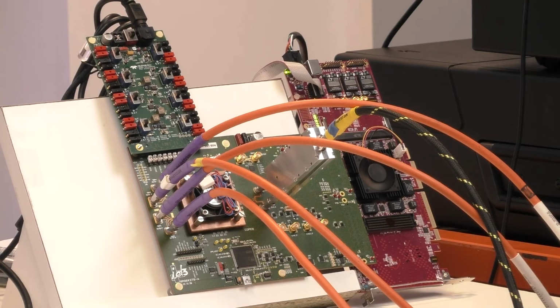Here, in our case, we are using the second solution. The DD700's cores start simultaneously, so we do not need to compensate this delay. This leaves the delay induced by the environment. The following method is proposed to compensate it and have two perfectly time-aligned signals, whatever delay is introduced by layout, connectors or cables.